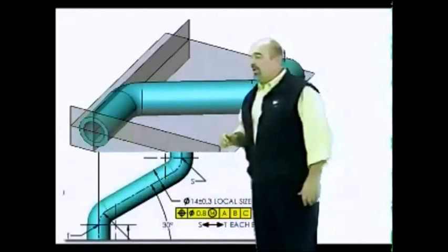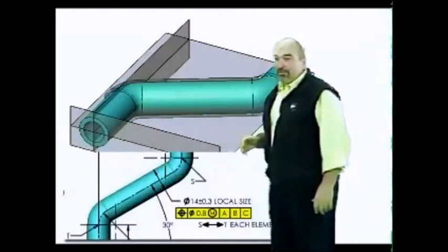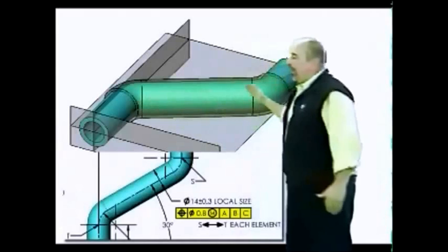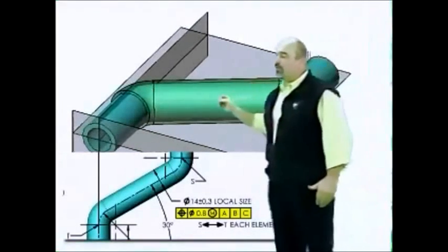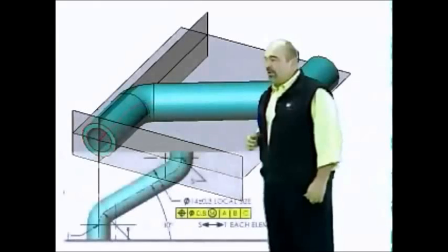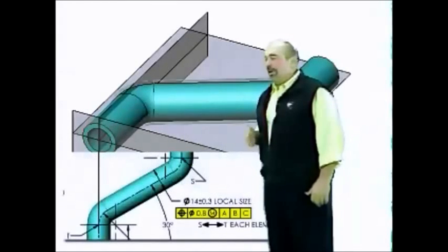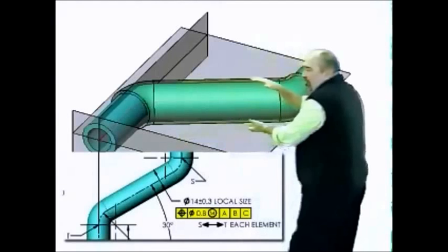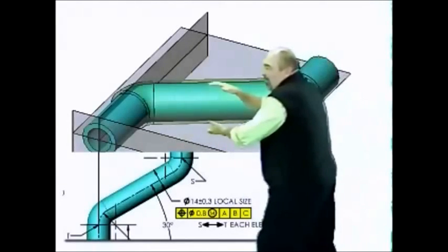The rest of the tube is controlled by the position tolerance applied to each element between points S and T. Each element or slice must be within 0.8 millimeters of its basic location if it's made at its largest size or maximum material condition. Together, these slices define a boundary that the surface of the tube may not go outside of.